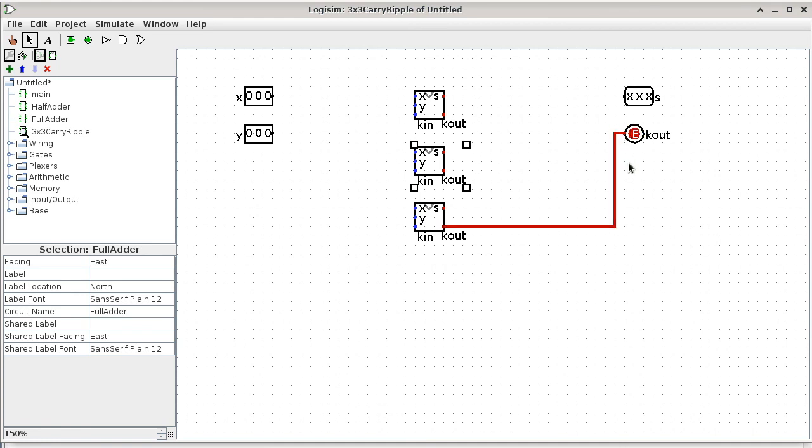That's pretty easy. There's an error because there are no inputs, and if there are no inputs, it cannot do any type of actual gate computation. So it's okay for it to have an error at this point. Not a big deal. We also know the output of one bit becomes the input of the other one. So we take this one out, and then we connect it to the input of the next one. We take this output pin. Now this is actually why it's called carry ripple, because you can see how it is forming a chain of full adders. This connection alone is causing what we call the rippling effect. Yep. This is the same thing as we were doing with the tunnels earlier.